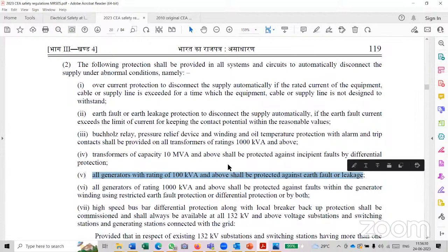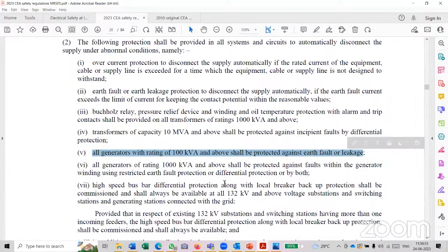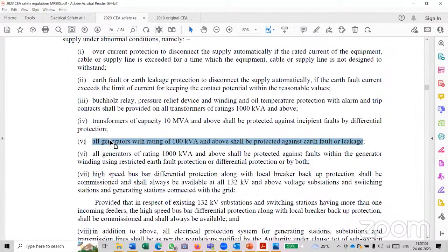Exceeding 650 means 11 kV in our system, at least minimum 11 kV. No 650 exists now. So we should not interpret it as voltage exceeding 650, because it is applicable for 100 kVA. There is no 100 kVA DG set at 11 kV, and an interlock is necessary for avoiding paralleling or feedback. So we should interpret it out of common sense and science, and technically we should not strictly abide by the regulation. It has become a compulsion.